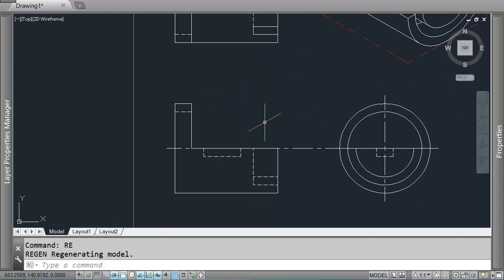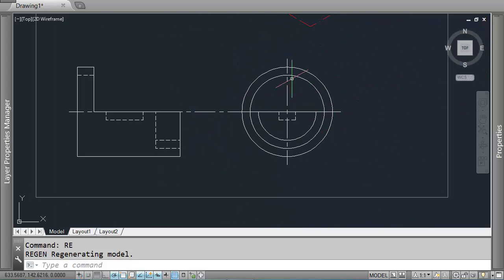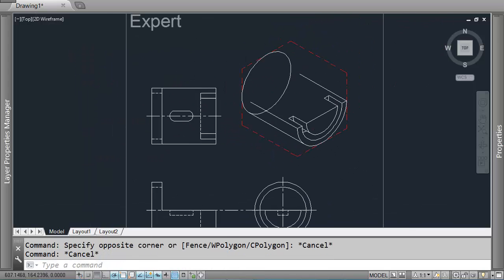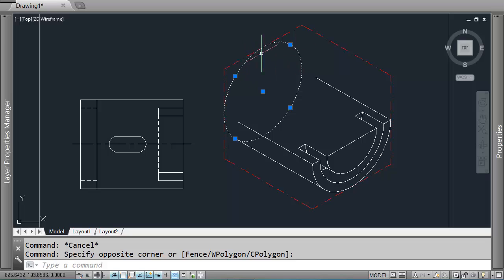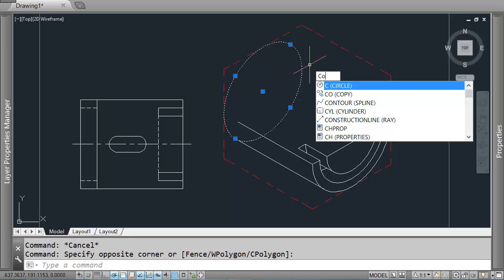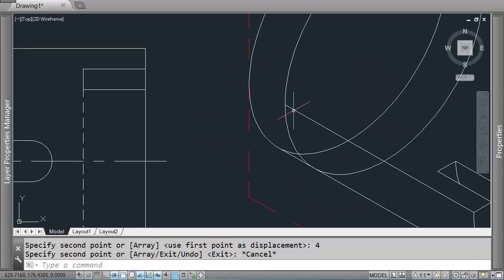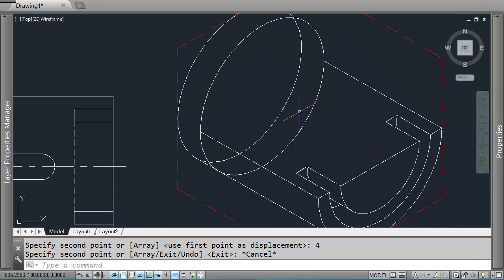So knowing that there is a high standing circle, I can see in this view that we have a high standing circle which is right up the back part of the shape, extends up this 4 units width. I'm going to grab the full ellipse that I have here and copy it forward through 4 units. You see that just lines up with those points there.